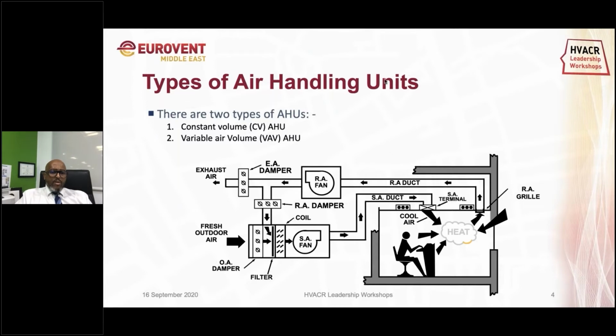And simply how it works, I have a simple diagram you can see here, gentlemen and ladies. The air is circulated through the duct, the grills and diffusers, and goes back to the AHU. There's a certain amount of fresh air that comes in from outside into the building. The whole purpose is to remove heat mainly, so it conserves comfort in occupied areas, whether transient areas or areas with a lot of movement.